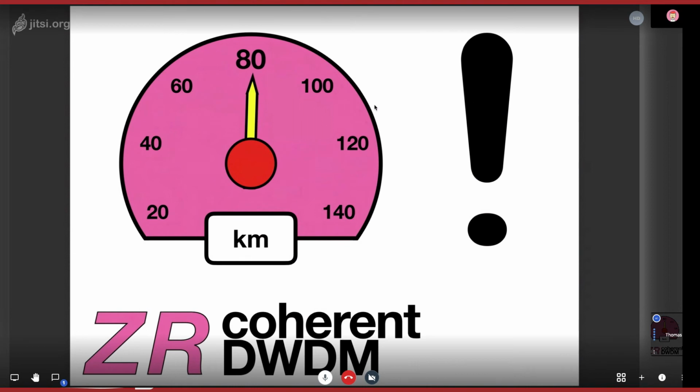Having seen that issue, the 400 gigabit standardization and also the people who design these form factors said, we need a way to build in ZR technology again so that we can reach 80 kilometers or even beyond that. Back in those days, with 10 gigabit, we had that capability. Now with 40 and 100 gigabit, we didn't have that capability. And the main driver was the power consumption or heat dissipation.